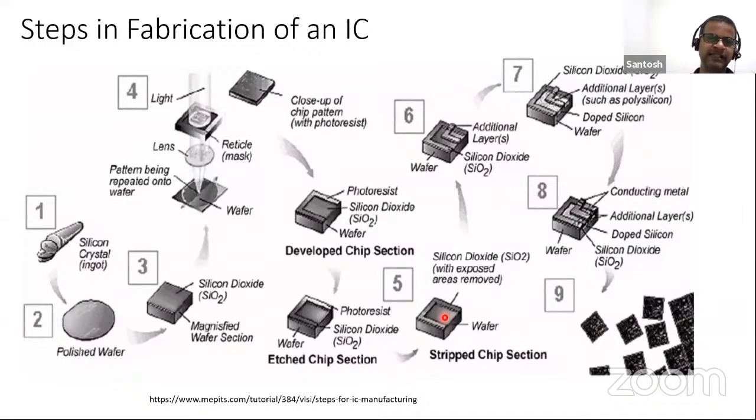The next process is, in this place, the doping occurs. The IC transistors are carrying a number of P and N junctions. The PN junctions are actually created using the process of doping. By continuous replication of photoresist patterning, removal of the photoresist and doping, continuous patterns are created.